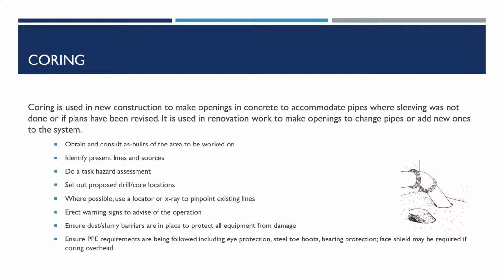Where possible, use a locator or X-ray to pinpoint existing lines. Erect warning signs to advise of the operation. Ensure dust slurry barriers are in place to protect all equipment from damage. And ensure PPE requirements are being followed, including eye protection, steel-toed boots, hearing protection. Face shield may be required if coring overhead.